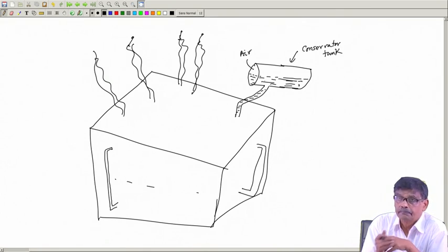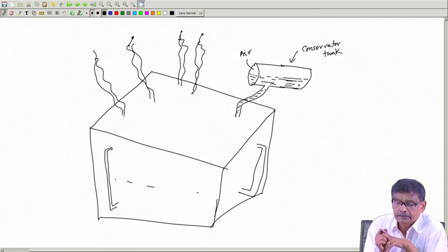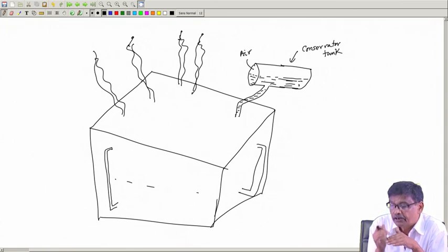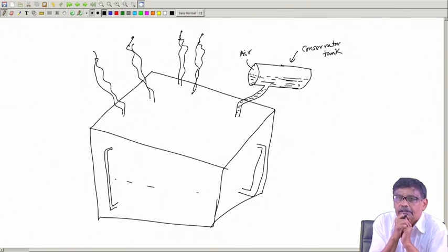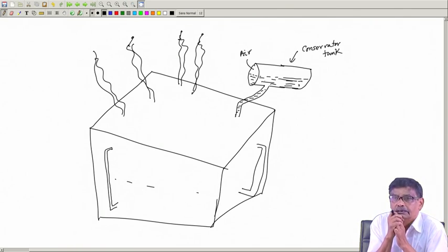Tank is a steel tank. Also among the turns, as you go from one turn to another, there are voltage differences, there exists voltage per turn. Therefore, a good insulating material you have provided. Air is also a good insulator, but this oil will be much better.